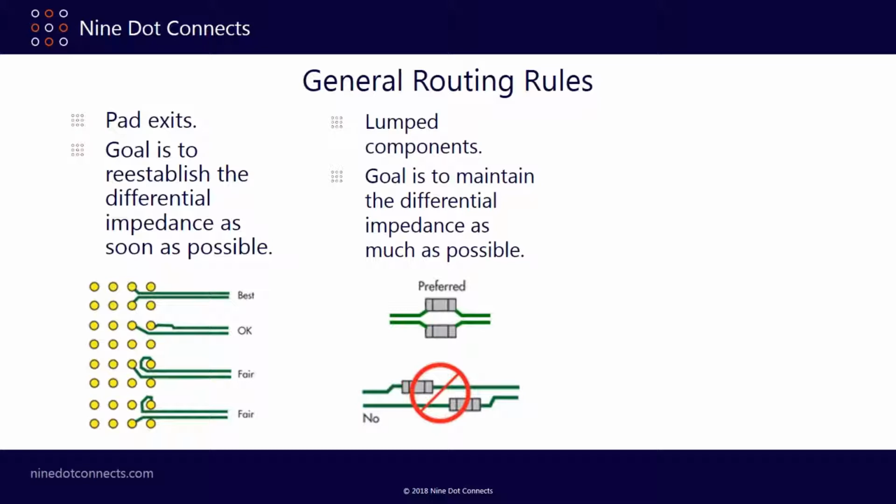Here's my thought on this whole concept as we go forward and you're looking at the slides. You can try and make sure you cover all your bases, so just in case you miss something, you have built in enough slop, made a little extra room for that slop. If you treat all these general routing rules as, it's probably not a big deal because that's a lumped length, not a transmission line, then they can all add up quite significantly.